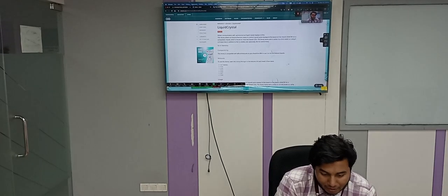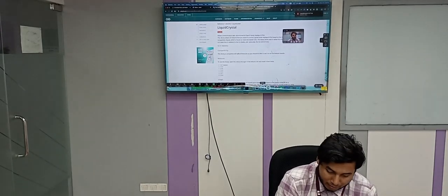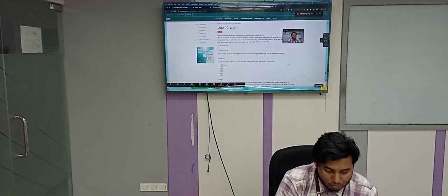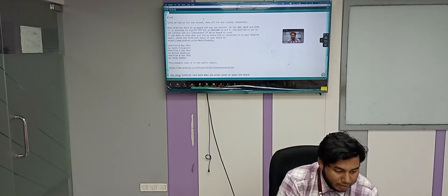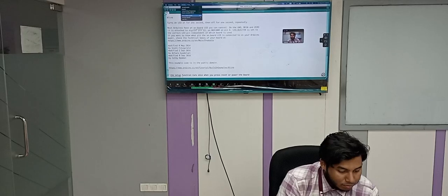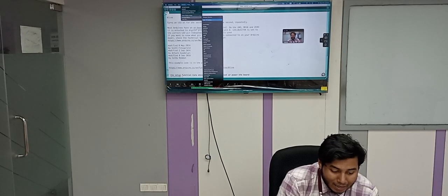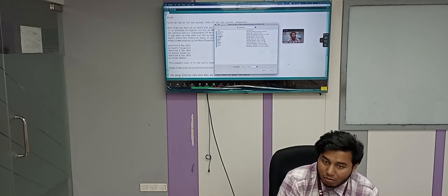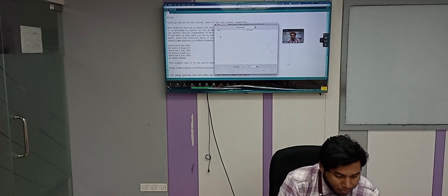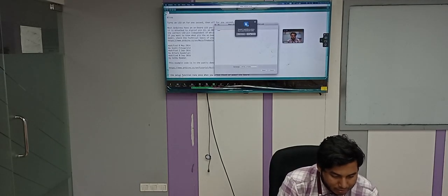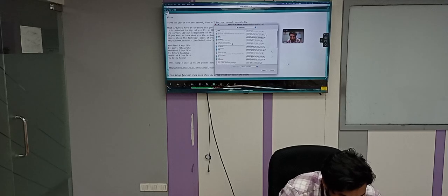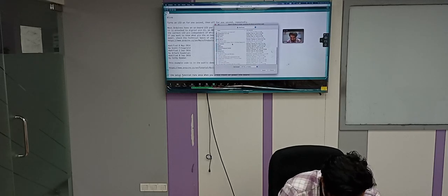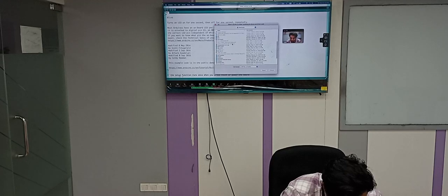See, a zip file has been downloaded. It's 90.5 kilobytes. So it has been downloaded to my laptop. The thing you need to do is go to the Arduino IDE, then the include library option, then add zip library. I know it has been downloaded to my downloads section, so I will enter my downloads section and search for the downloaded file. Where is it?